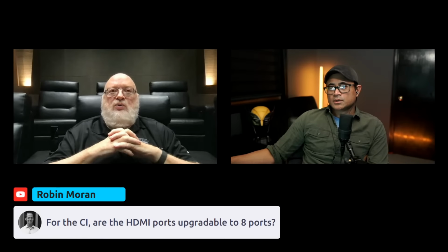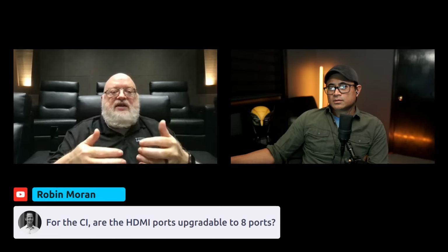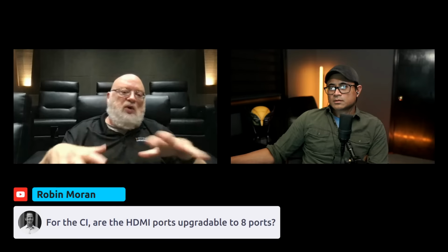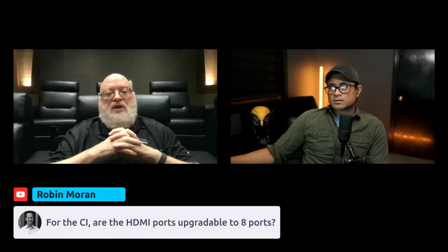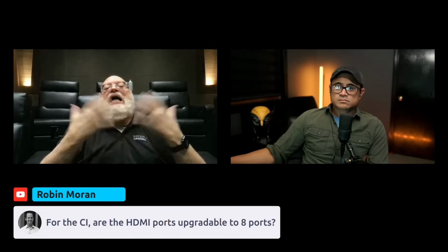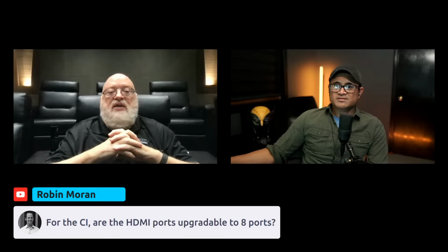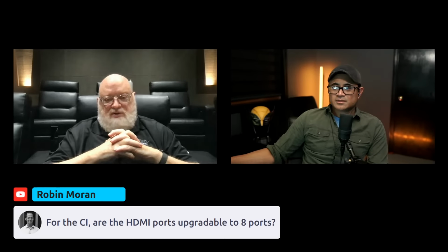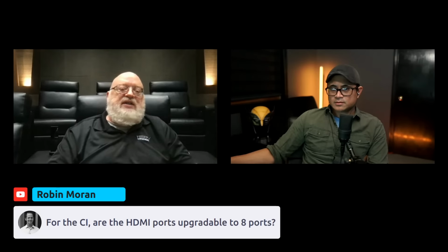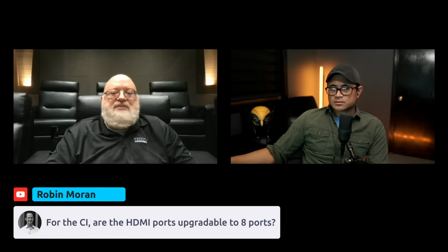Anybody who understands the necessity of electrostatic discharge precautions when you're working inside of flying electronics and so forth should be able to do this. I mean, I can do it, for heaven's sakes. I've done it on customers' kitchen tables. So you need a static strap. You need to pay attention to ESD, but it's not hard.